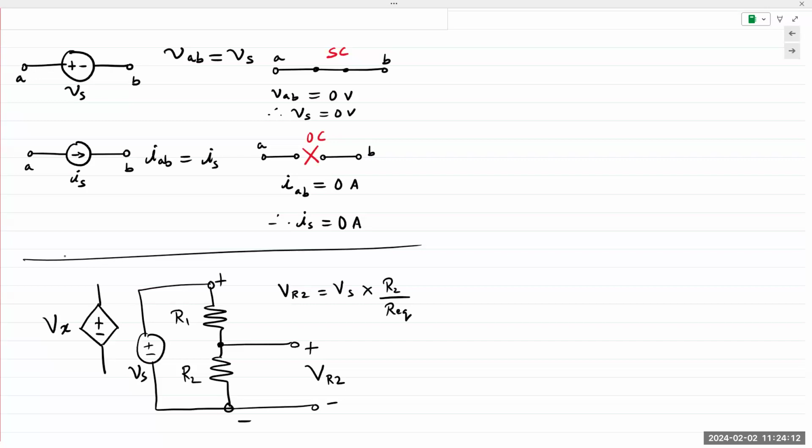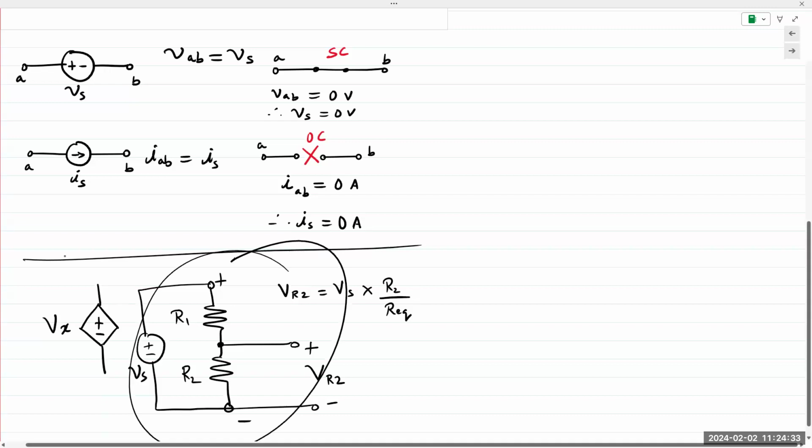Okay, 19.5 volts. So a single line of 19.5 volts goes into your laptop, but a laptop requires 5 volts. It requires 3.3 volts. It might require like 10 volts for running a fan, perhaps. It requires multiple voltages. That's where we would use a network like this. You would take the 19 volts, you would break it down into multiple different parts, and each part would be a dependent voltage source. It will supply, for example, 5 volts to a USB port, but that 5 volt source is dependent on the 19 volts coming from the laptop adapter.